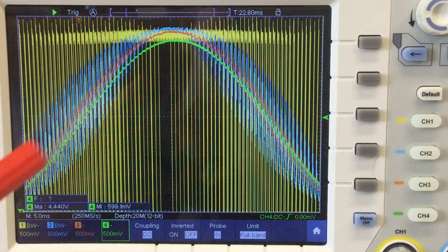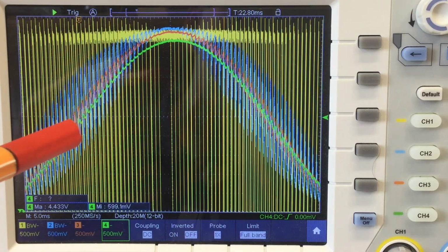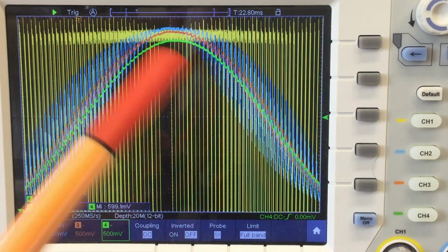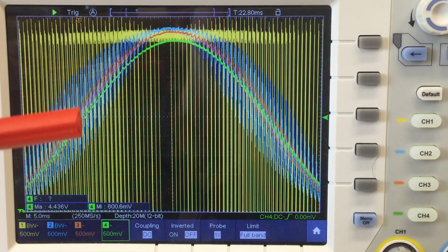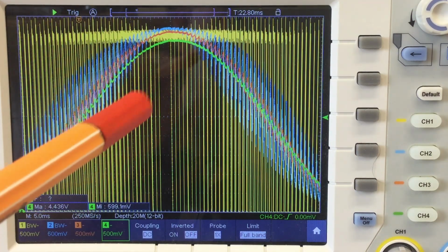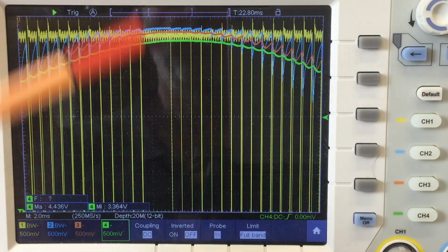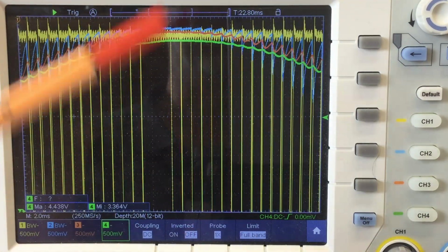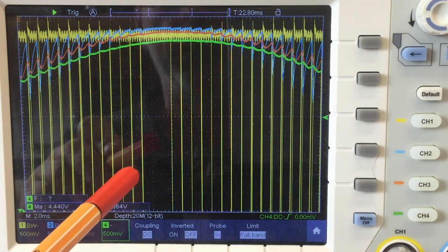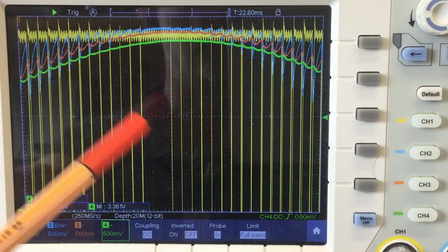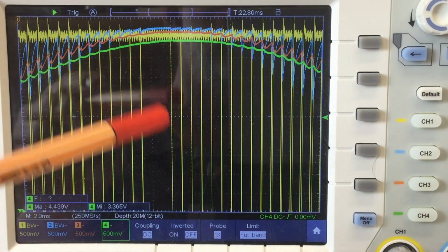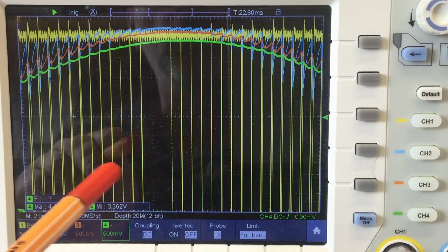But very sine wavy. And of course we will measure the ripple to check if our design really met our requirement in regards to that 1 LSB maximum ripple in there. But let's zoom in a little bit more. Now you can see, or at least guess, the phase shift that is generated by all those RC elements. I mean, we are operating then at about-ish 7 times of their cutoff frequency, so the phase shift of each RC element is approaching 90 degrees.